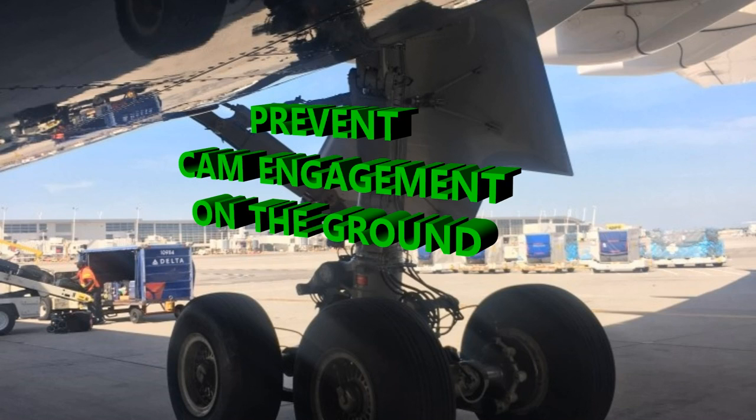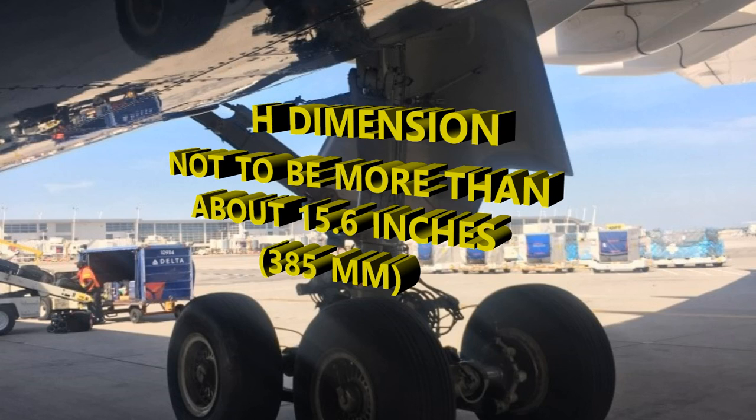But what happens is you want to have a measuring or reference point with the H dimension, and if it's more than 385 millimeters, roughly about 15.6 inches, then you're liable to cause damage to the retraction part. So that's just a precaution when you're doing any kind of towing with the aircraft or pushback. Just know that you could have a problem with the damage.